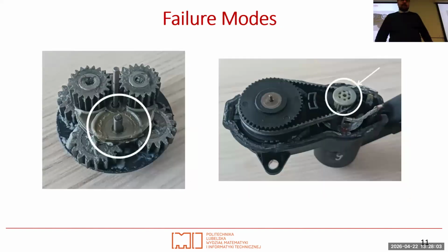However, what is inside, I'm referring now to the failure modes. When you open up the upper part, you can see there are a couple of things inside. Below this pinion there is an electric motor combined with the mesh, and also a tooth belt going to the planetary gearbox that is going out. And here I want to refer to some failure modes that we have.